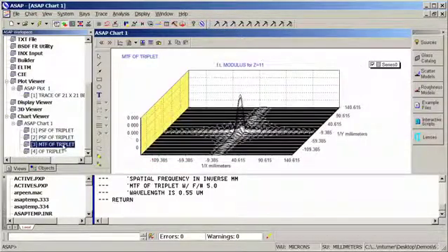And what we can see with the MTF plot, and let's take a look at the three-dimensional plot, is the fact that this optical system designed to operate over a 30-degree field of view is not anywhere near diffraction limited, and we're seeing the effects of the aberrations in this optical system. And again, we can compare this to the lens design program itself and make sure that indeed the performance as defined by the ASAP system matches that created in the lens design code.